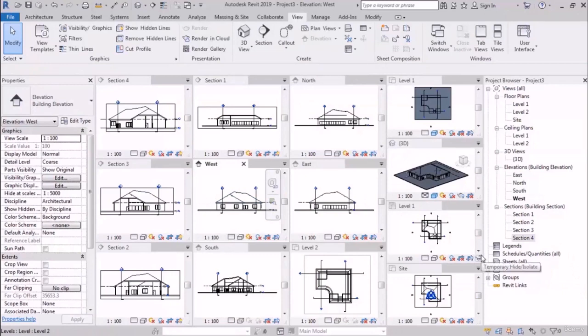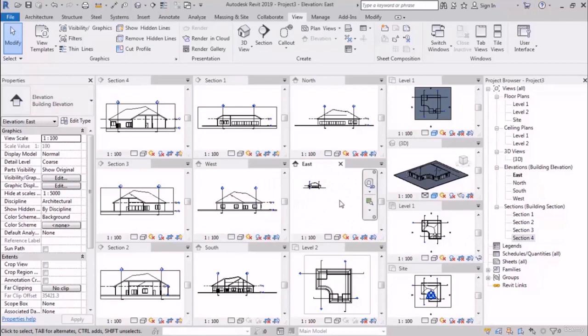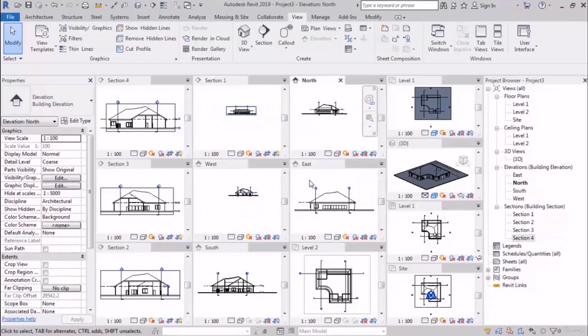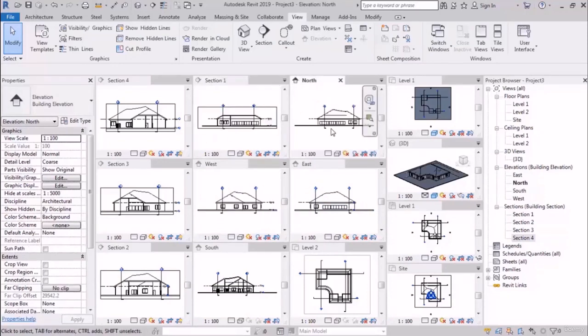But if you just want to do the zoom extend in just one of these, you can press ZE and it does the zoom extend in just one of them. So it will be ZE. Or another way is to double click on your scroll. You can see it works this way too. But it doesn't seem to be that useful.